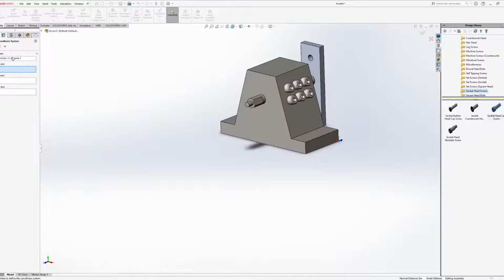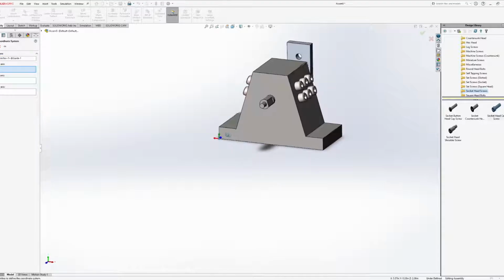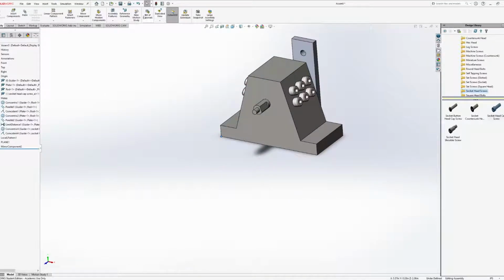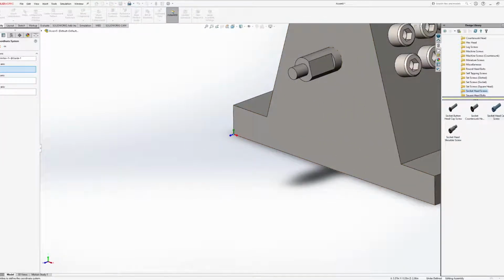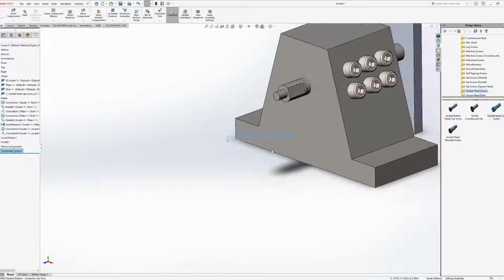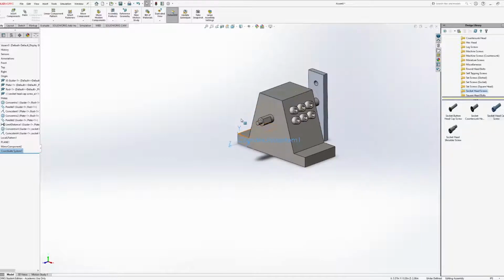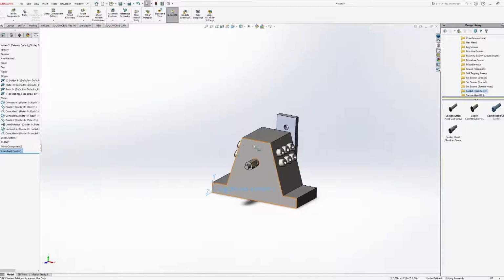For the time being, I'm going to leave those as is, and I'm going to replace this one more time on the global. In fact, I'm just going to reset it so that it does things the way that I want it to. So now I have a new coordinate system, and I'm going to hit OK. You can see it here. Our x direction is along that axis, our z direction is normal to the face of the guide, and the y direction is effectively the height.